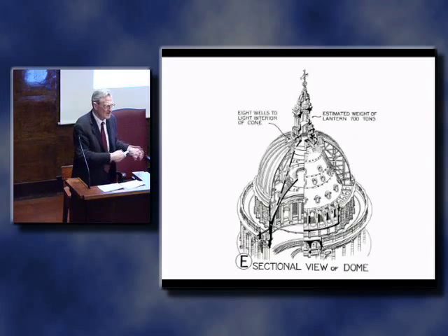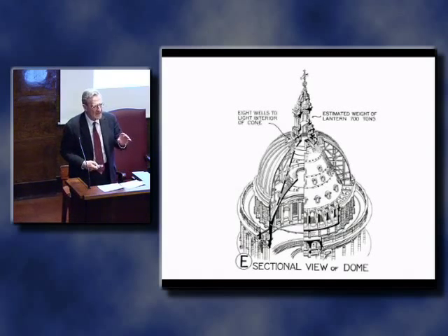The thickness of the dome here, marked in feet and inches, is in fact 460 millimeters. Conveniently, the radius divided by the thickness is 50. And the number of 50 defining the thinness of a structure, it certainly is thin. In fact, membrane theory, about which I will talk a little this morning, assumes that the ratio of radius to thickness is 20 or more, so that 50 is certainly thin. And we make some assumptions there, which we must be very careful of because they can be misleading.